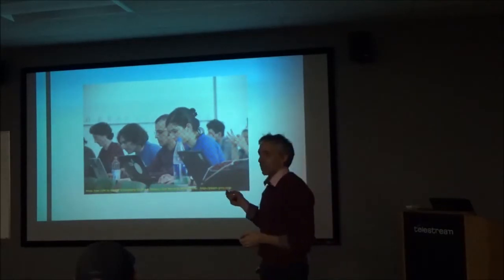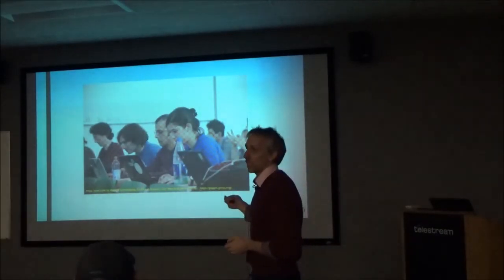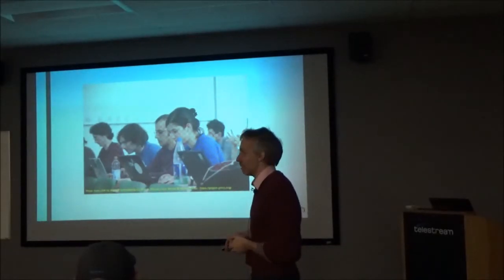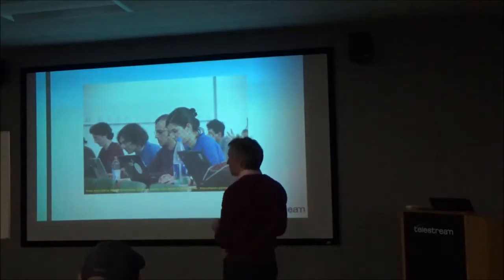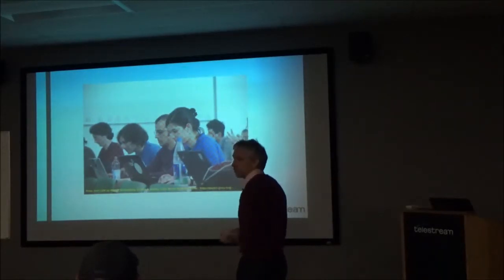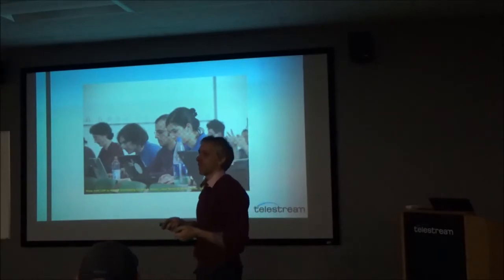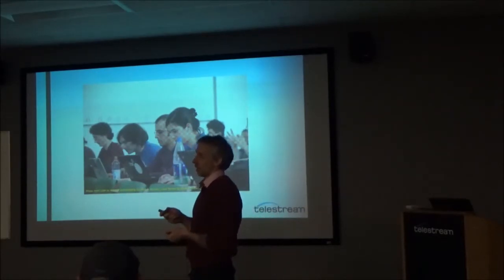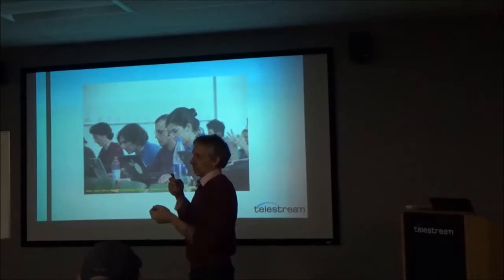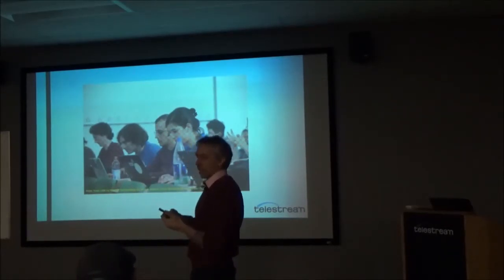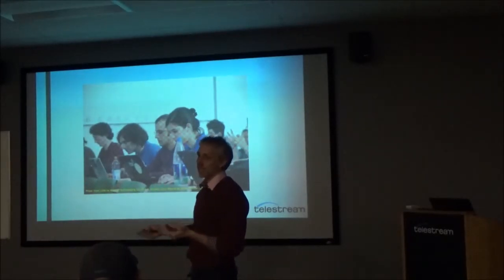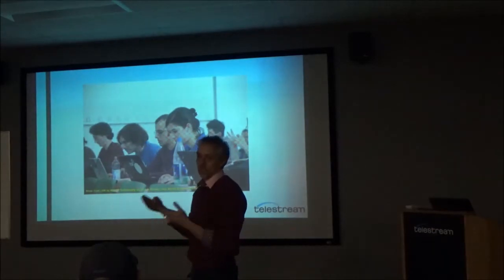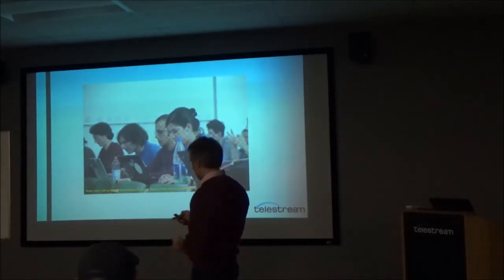Okay, you may have seen this on the internet, maybe not. It's one of those optical illusion things. It looks like what you're seeing here is a color image, sort of. But what it actually is, is a black and white picture with some diagonal lines of various colors on it. It's supposed to represent the fact that your eye sees black and white luminance levels at a greater granularity than it sees chrominance color information. So you can get away with transmitting less color information and still get a good subjective experience.